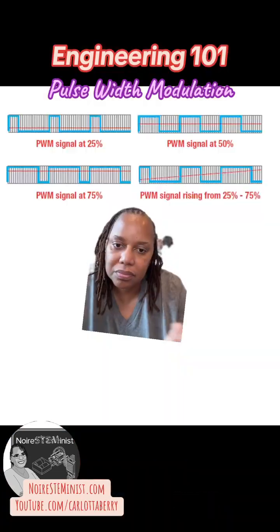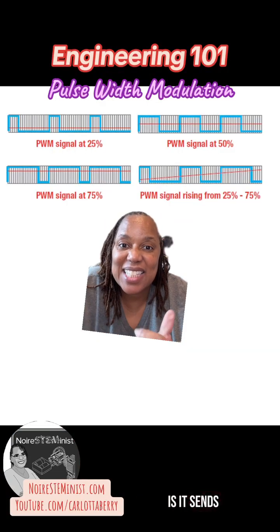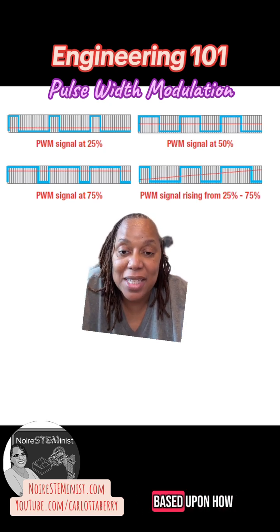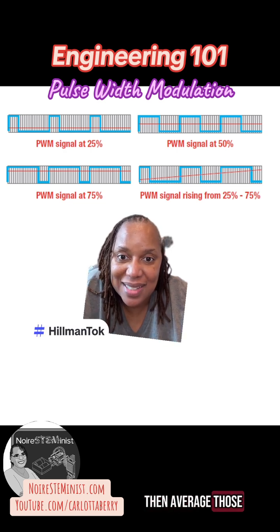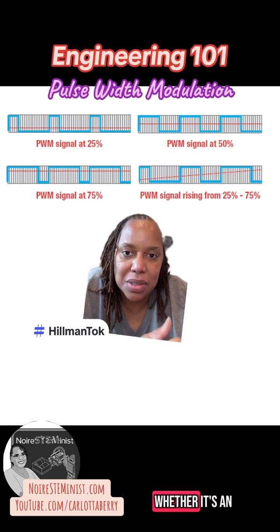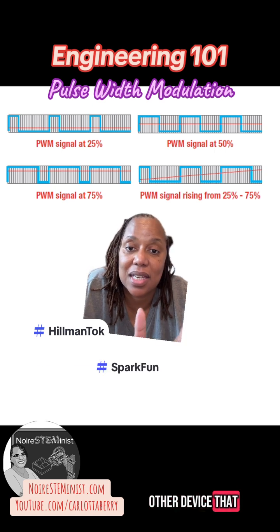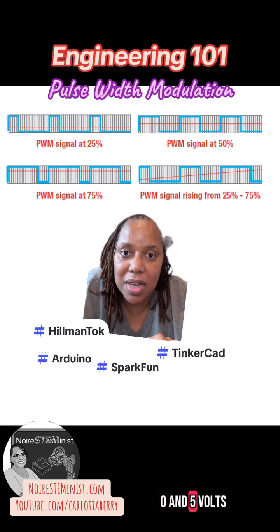So what pulse width modulation does is it sends a series of ones and zeros really, really quickly. And based upon how fast and how many, the computer will then average those to send out a signal. And so what your device sees, whether it's an LED or a buzzer or any other device that reads analog data, is it reads some number between 0 and 5 volts.